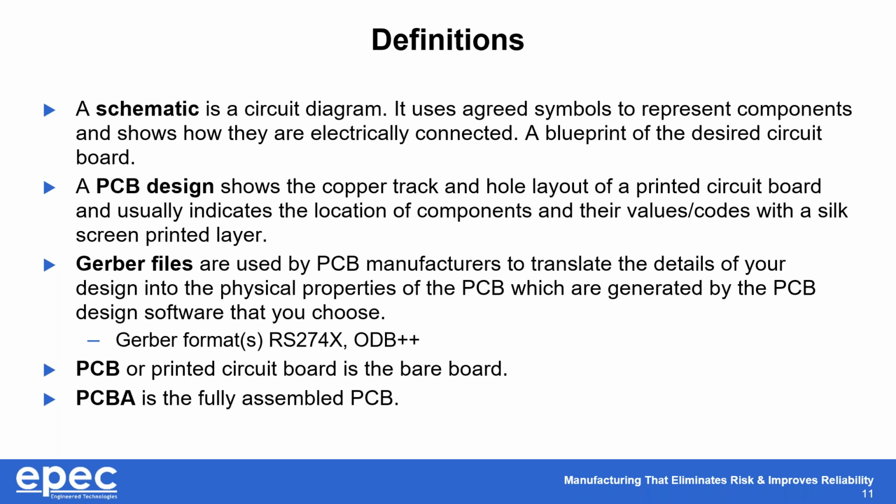Gerber files used by the PCB manufacturer are data to create all the layers that are needed to fabricate your PCB. The circuitry layers for all copper internals and externals, solder mask for both sides, silkscreens for one side or two, and an outline layer, as well as the drill, non-plated drill, or perhaps you have some blind vias or buried vias.